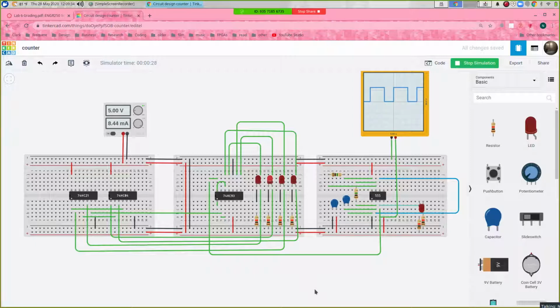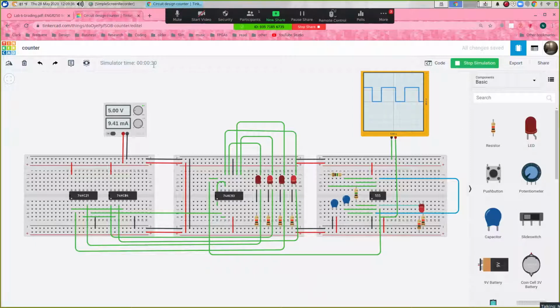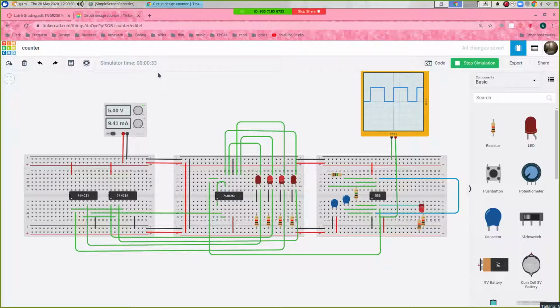But when I tried this at first, I was having the issue where the simulator was hanging up when it tried to roll over from 10 back to 0. And then I changed the capacitor, and I changed it back, and I changed some other things, and now it seems to be working reliably. The fact that the simulator time was freezing or going very slowly suggests something was unstable in the circuit configuration or in the simulator's analysis of it. But as I told people, that's what you put in your lab report, as your observation. That's perfectly valid. But it is workable.